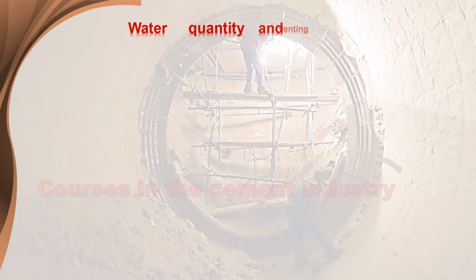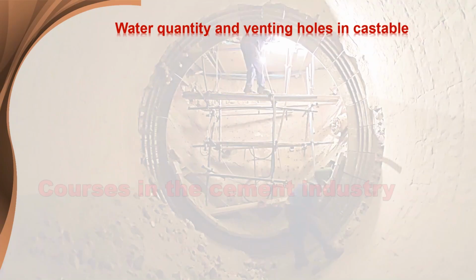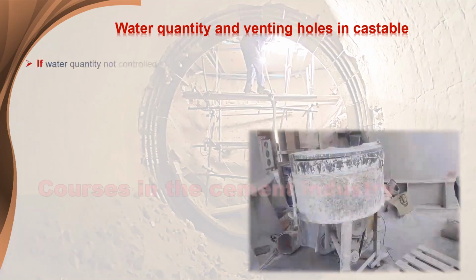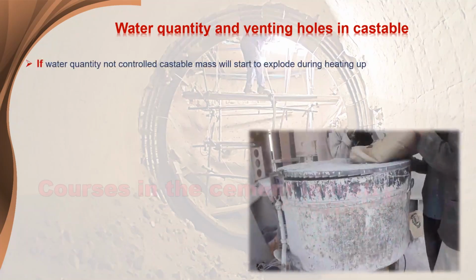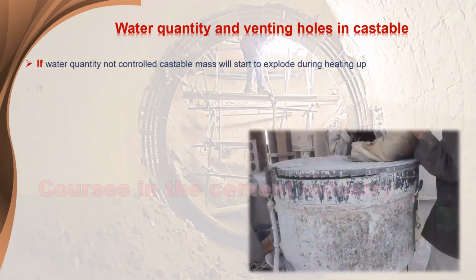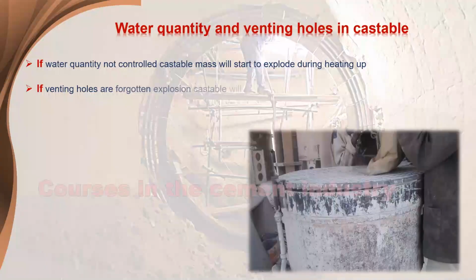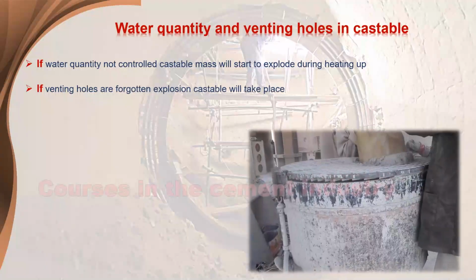Water quantity and venting holes in castable. Please read these very important notes. 1. If water quantity is not controlled, the castable mass will start to explode during heating up. 2. If venting holes are forgotten, castable explosion will take place.